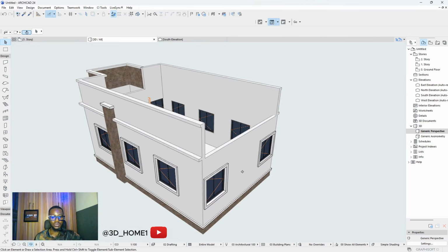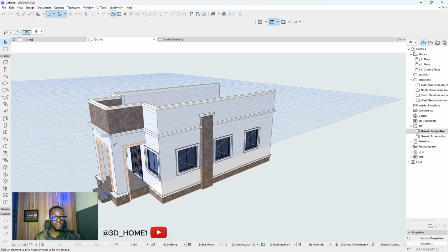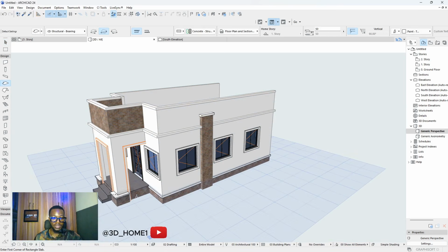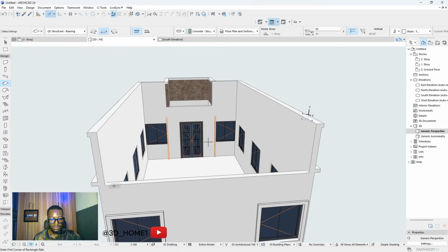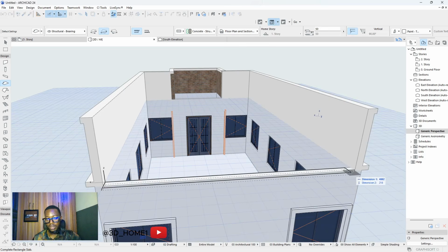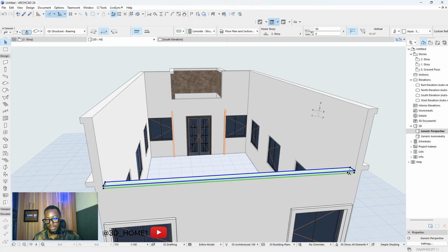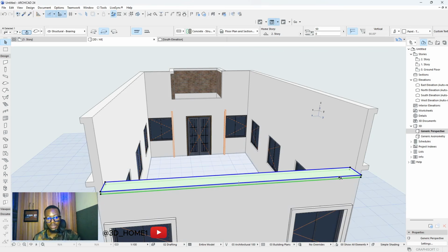What we'll do now is we'll just select, we'll use slab for it, okay? Use slab, click pick up parameter. You see that I use a lot of pick up parameters so that the work can be fast. So I'll just click on orbit, click from here to here. Then click here, then later click here and stretch it, no, just one side. So I'll bring it to 200 and I'll add the thickness to maybe 150. So that's it.